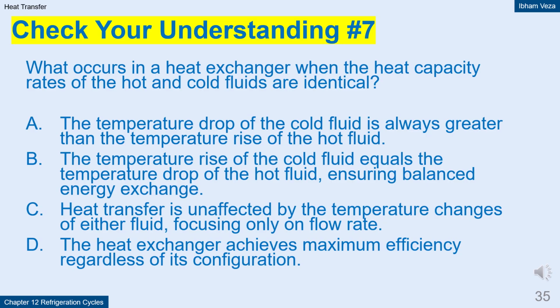Correct answer, B. The temperature rise of the cold fluid equals the temperature drop of the hot fluid, ensuring balanced energy exchange. Explanation of incorrect options. A. The temperature drop of the cold fluid is always greater than the temperature rise of the hot fluid. This is incorrect because when the heat capacity rates are identical, the temperature changes of the two fluids are equal,